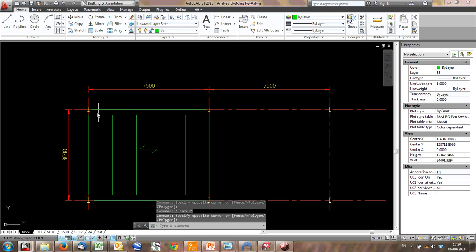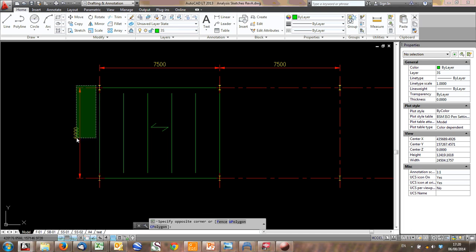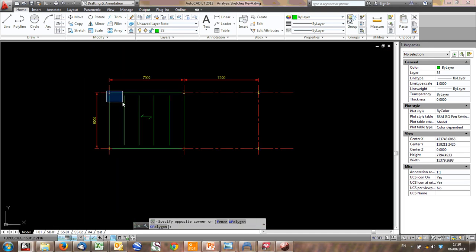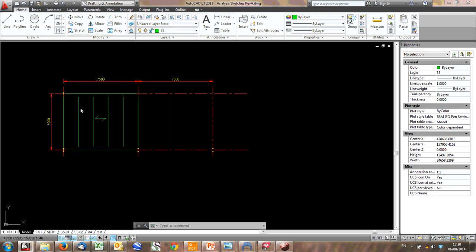And if you want to size that one quickly, this is basically a UDL from here to here. So you can just take the width, which would be 3 meters, halfway between, or if this slab sticks over, it'd be a bit further than 3. You apply it. And that way you can very quickly size floors. And once again, steel work, you normally size for deflection and check strength. So you can get an idea of what size you're doing.